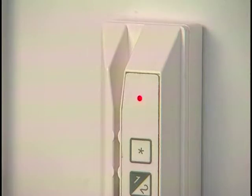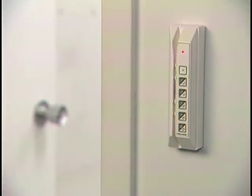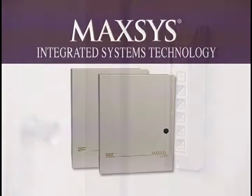The reader will wait up to 10 seconds for a privileged card to be presented. A rapid flash, 4 times a second, indicates that access has not been granted. Either the card is invalid or is being used outside of the scheduled time. The buzzer will sound continuous if the door has been forced open or has been open too long. To silence the buzzer, close the door. The buzzer will also beep once every second during the last half of the door open time to alert the user that the door must be closed.